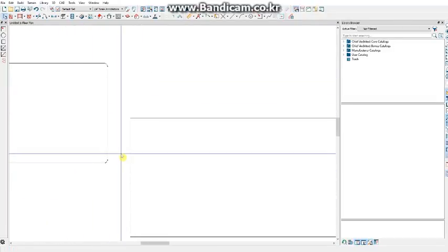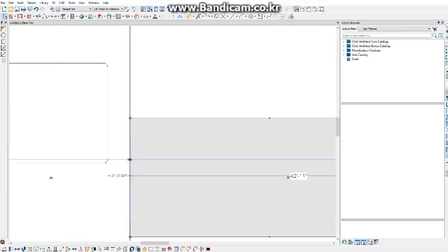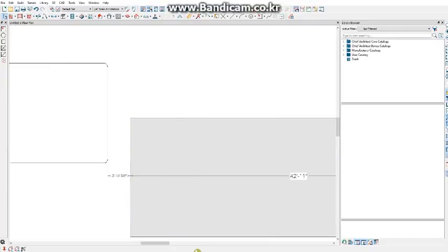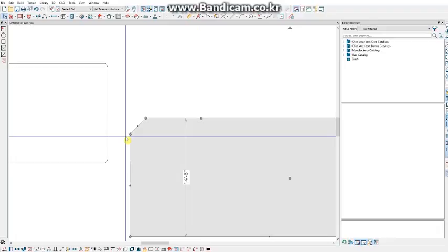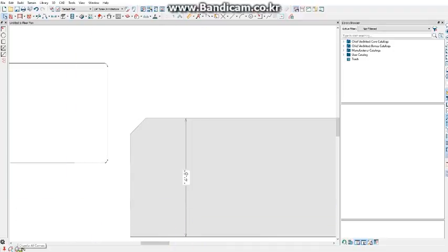You also have your chamfer tool. If I select this polyline and then click on the chamfer tool, this tool behaves very much like the fillet tool. If I click on the Set Chamfer Distance tool, I can change the chamfer distance and then click OK, and then click on one of the connected lines. That will bevel or chamfer the corner to that exact distance. Again, I can use that chamfer tool, and I can chamfer or bevel all the corners of this object.